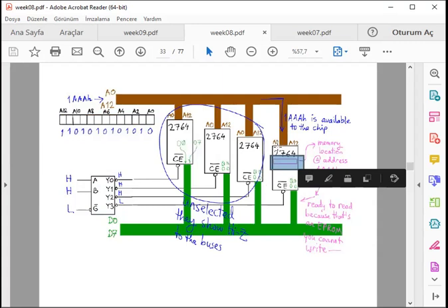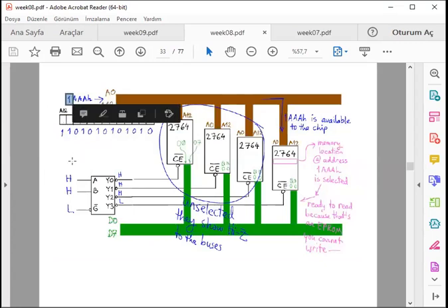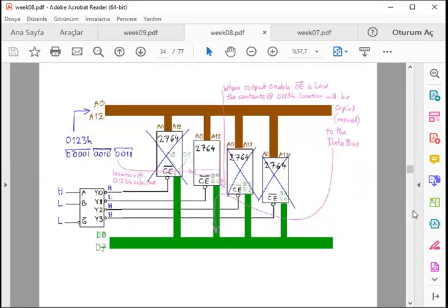So addresses start with all zeros and go up to all ones, or 1FFF for the 13-bit address. The maximum address is 13 ones, meaning 3 nibbles, 12, plus the 13th one. So we cannot have an address over 1FFF.